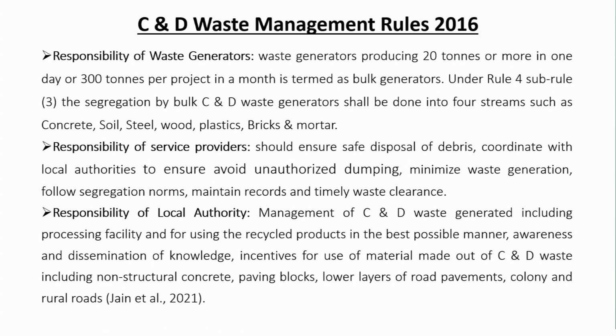The next responsibility is of the local authority: management of construction and demolition waste generated, including a processing facility, and using the recycled product in the best possible manner, awareness, dissemination of knowledge, and incentives for use of material made out of this waste, including non-structural concrete, paving blocks, lower layers of road pavement, colony and rural roads.